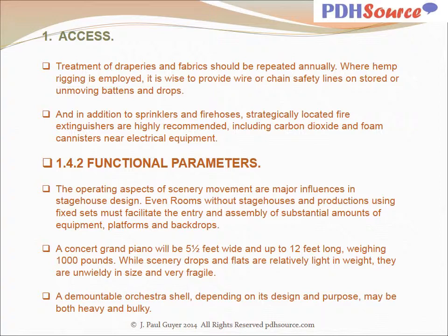With regard to functional parameters, the operating aspects of scenery movement are major influences in stage house design. Even rooms without stage houses in productions using fixed sets must facilitate the entry and assembly of substantial amounts of equipment, platforms, and backdrops. A concert grand piano will be 5.5 feet wide and up to 12 feet long, weighing 1,000 pounds. While scenery drops and flats are relatively light in weight, they are unwieldy in size and very fragile. A demountable orchestra shell, depending on its design and purpose, may be both heavy and bulky.